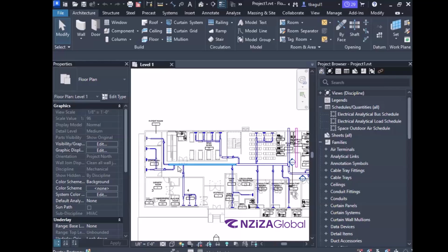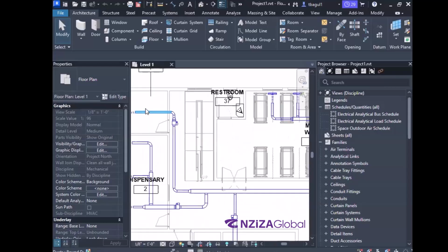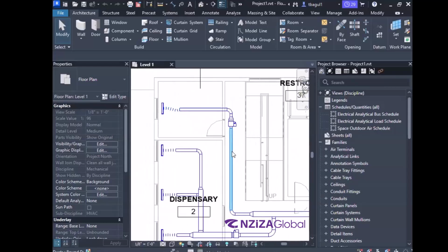But we need to make sure that we have certain minimum standards that we need to follow, right? Like yesterday, we spoke about the maximum 5 feet length for the flex duct. Please make sure that you try to apply that as much as possible. Now, we will talk a bit about sizing the ducts. I understand you might have sized the ducts with what the neck size is or what the inlet size is of the VAV box, correct? That's how you sized the duct till now. Next, we are going to size the duct based on the pressure drop that is being designed for.